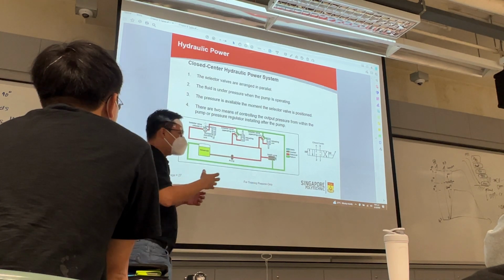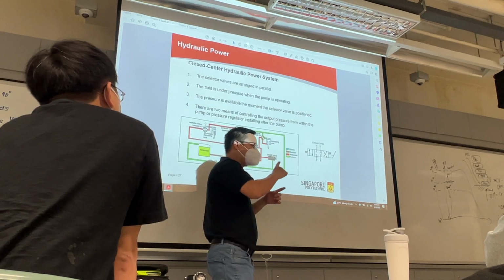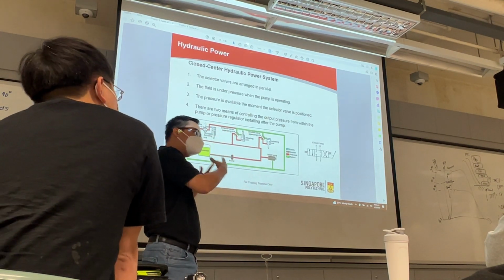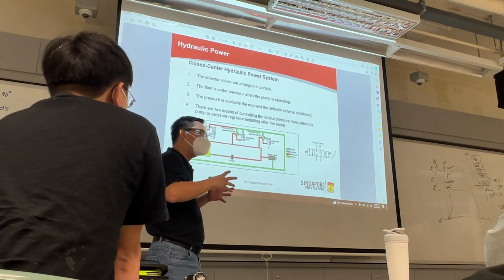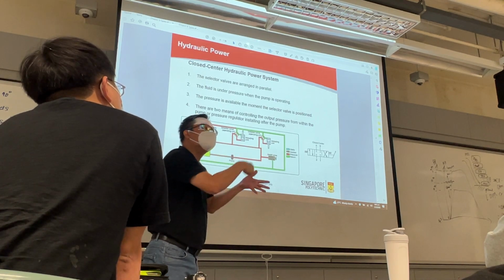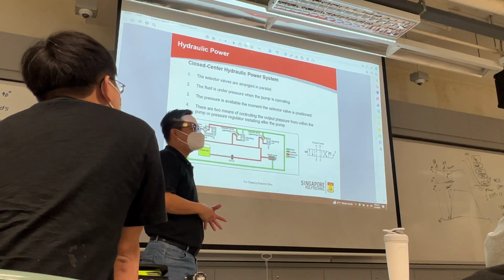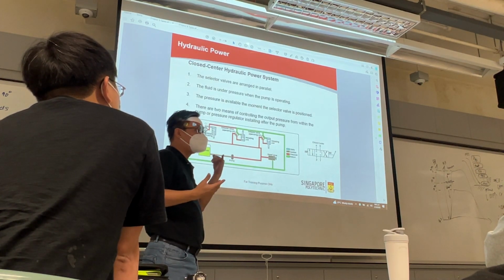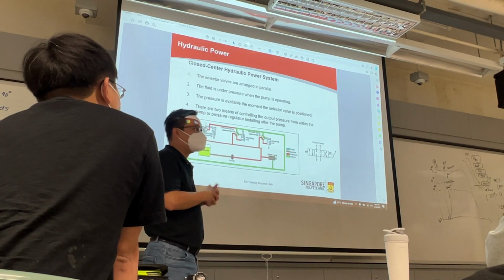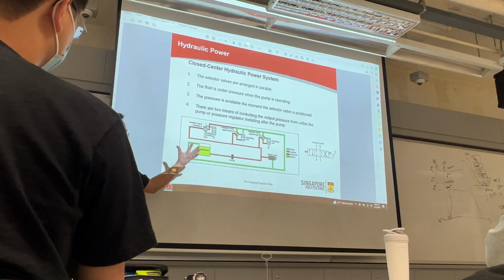You know why? When you operate both systems at the same time, it will fluctuate, because the landing gear is very heavy, and your flaps are also very demanding. So the pump may not have the capacity to give you the flow. Fluctuation is normal. In your flight manual, you're supposed to do one at a time. Then at the end of the day, we have to check out the aircraft, wait 6 hours, do a landing gear swing, and make sure it doesn't fluctuate. So my point is, the pump is also not designed to give you very big capacity.